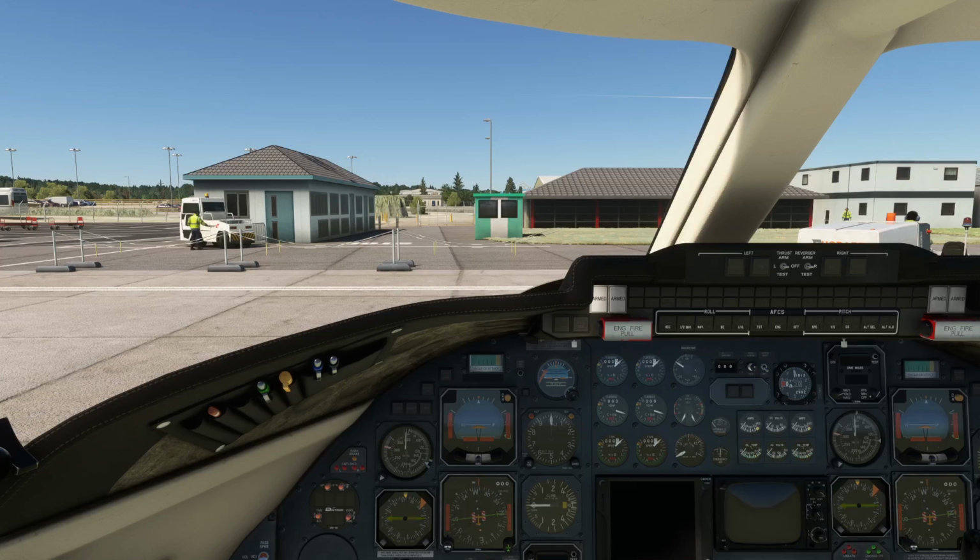There's the ground power unit that will supply the electrical needs of the aircraft as well. And the very final source of supply, if all else has failed, is a single emergency battery that will provide supply to some of the most basic and essential systems like the standby flight instruments and the electrical circuitry for the landing gear and the flaps.